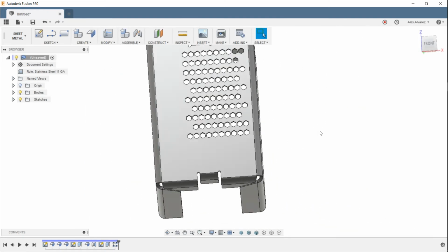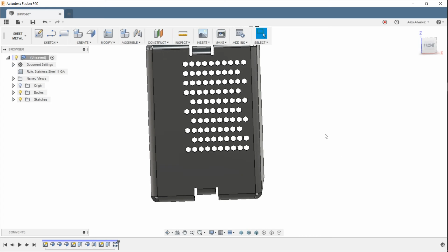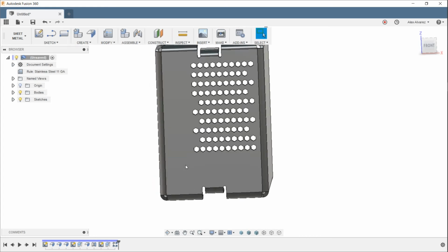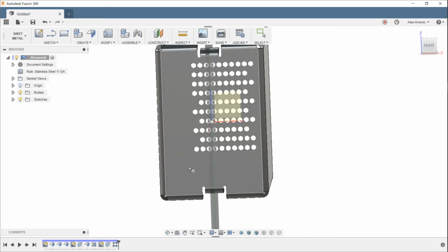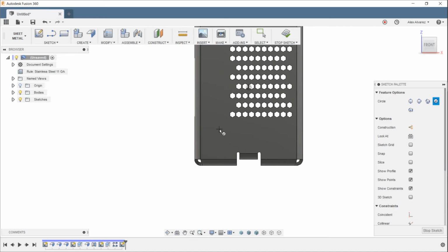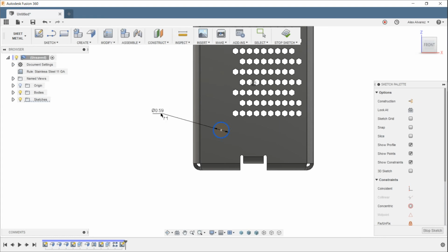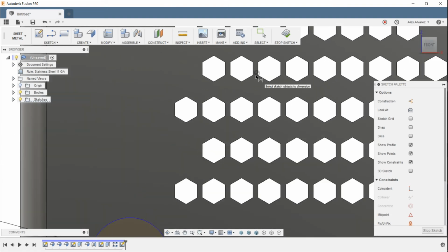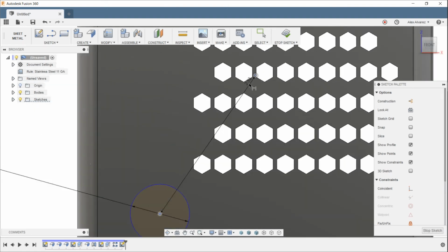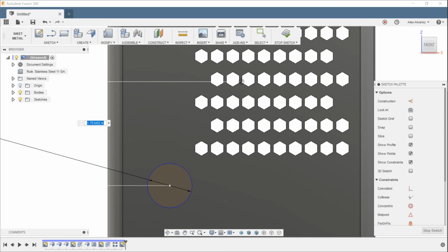our cutouts, right? So really, the last step here then is creating that hole. Right, so again, let's create that hole here. C for circle. And then notice also that I'm not having to create a flat pattern, right? Or unfold it and start refolding it. Again, I'm working on the same face that I started off with, so that's always going to be my stationary face. So I don't need to go back in here and create some sort of an unfold feature in order to create these cutouts, right?